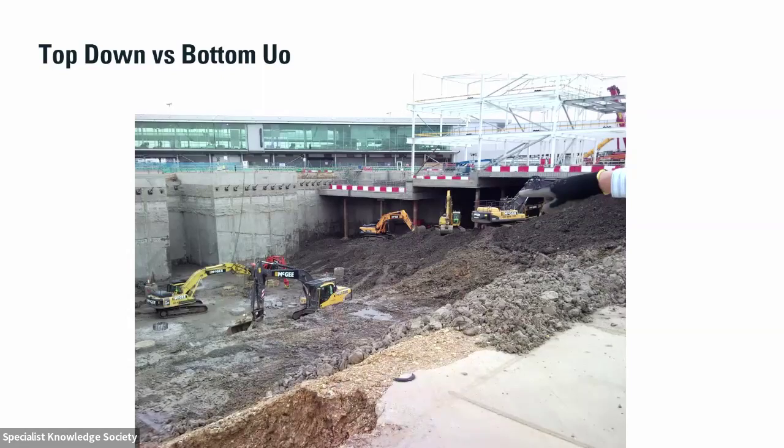But the superstructure's already flying. The superstructure's away. So if the superstructure is needed to be there while you're excavating below, and that eases the program, that would be the way to go. And I think that nicely shows that you're obviously down at the basement level in your bottom-up solution, but you're still excavating in your top-down solution because it's much slower, but you have your superstructure already constructed.